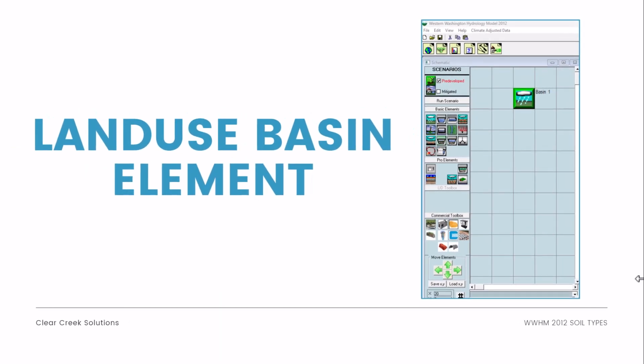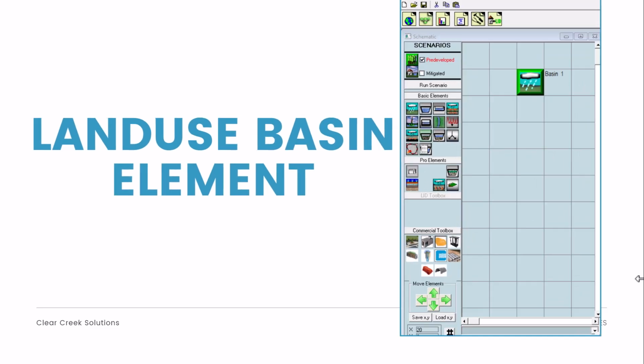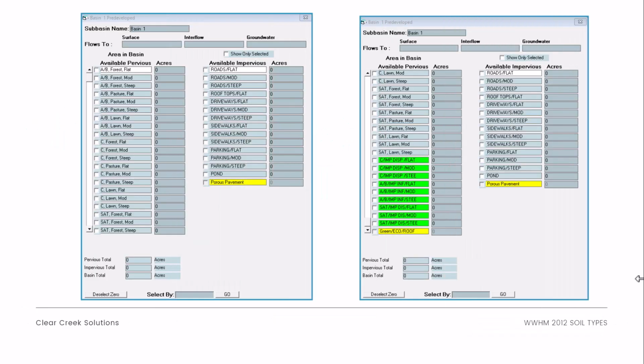Now, how do we represent land use area in WWHM 2012? We use the land use basin element. You can see here, you left click and you can drag the element into the modeling space. And that's where you can input your land use area. You can have as many basins as you want in your project. When you open up the form, this is what it looks like.